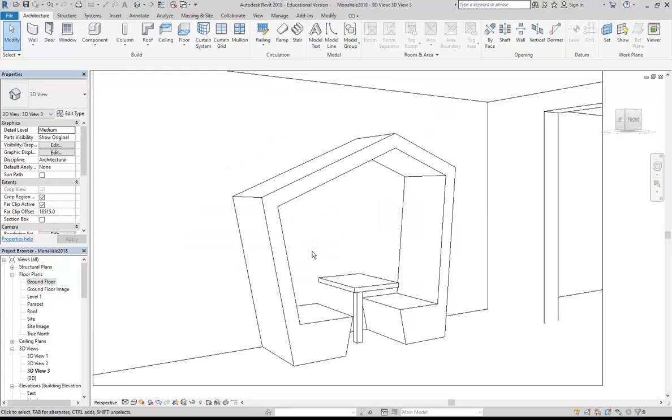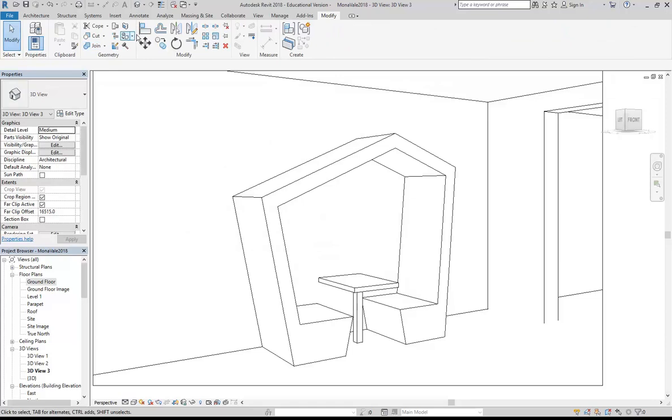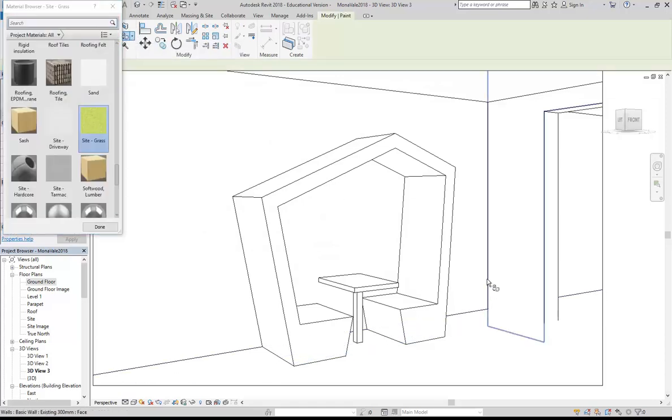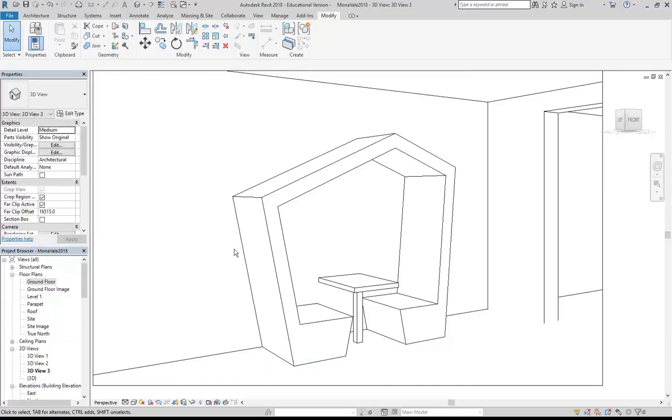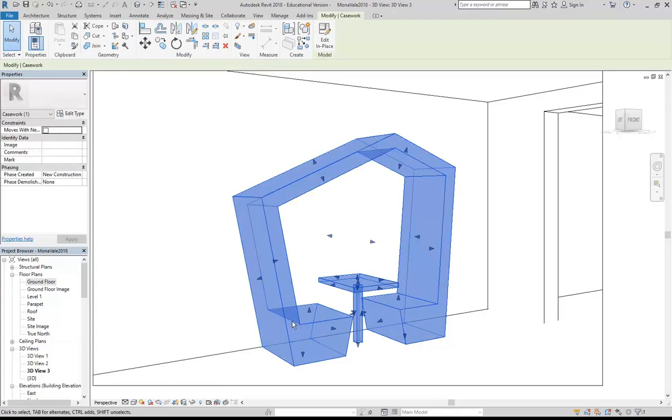No, that paint won't even work here. So I know a lot of people get shown paint. I'll show you what happens if you go to paint. I can choose the wall and the floor. Can't choose this thing. There is a way to use paint with it, but it's not going to work on its own. So what everyone forgets, well, a lot of people forget, is that you need to select the object and then go to edit and place to get back to the part where you can assign the materials.